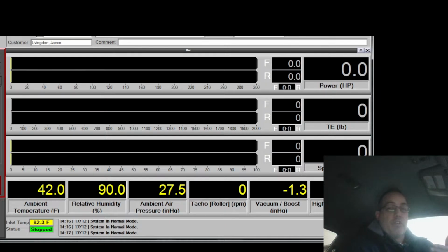And if I have more molecules that are starting to burn at the spark event, then I've already got a head start on my combustion. If you think about those exponential growth curves where 1 turns into 2, 2 turns into 4, 4 turns into 8, right? 8 turns into 16. Well, each of those steps takes time. If I start at 16, well, I'm going 16, 32, 64, right? Like I'm already forward on that curve. So gap affects burn speed.